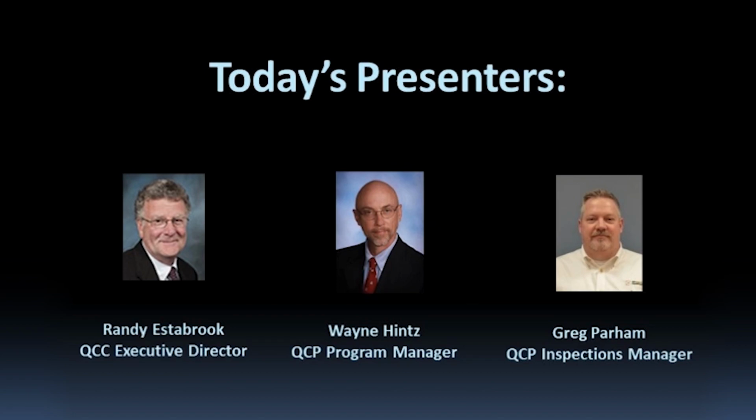I was involved in, or I should say QCP was involved in a project in, I want to say it was Florida or Louisville, maybe, somewhere down there. And it was a performing arts center, and it was a LEED project. So during construction and installation, they had the space sealed, and they were bringing in 100% outside air, which was, I think, 75% relative humidity. So there's another issue, and I don't know if that's still a requirement in LEED projects or not. Maybe in interiors projects where there's other tenants in the building to try to manage that airspace, but that can be catastrophic to have a situation like that.